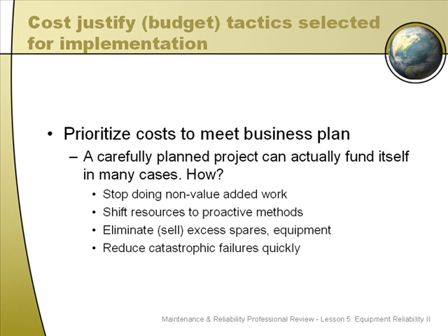Spare parts in the storeroom inventory. As you build your criticality table for your equipment and get a good understanding of where your high, medium, and low criticality equipment is, you can go through an analysis after building your bills of materials to find out which equipment can have less spare parts in storeroom inventory or have them completely eliminated. It's really important that you get the spare part inventory down in your storeroom, because while you have a lot of spare parts, all you're doing is fostering reactive maintenance. If you don't have a lot of spare parts, it really forces the organization to plan, because you can't do work without parts.